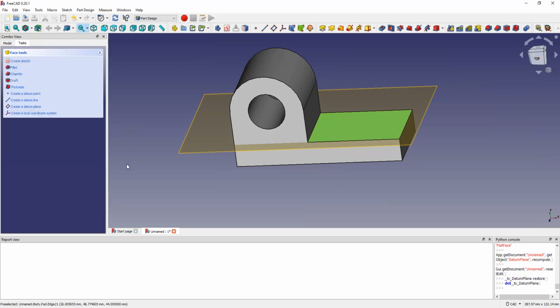After you press OK, what next? You create the body. You create a sketch here. Never confuse creating a body and creating a sketch. They are different. When you want to create a body, you start from the point whereby you choose the Cartesian plane to use: XY, XZ, YZ. You see? But when you want to create a sketch, it means there's already a process running. So in this case, we create a sketch.